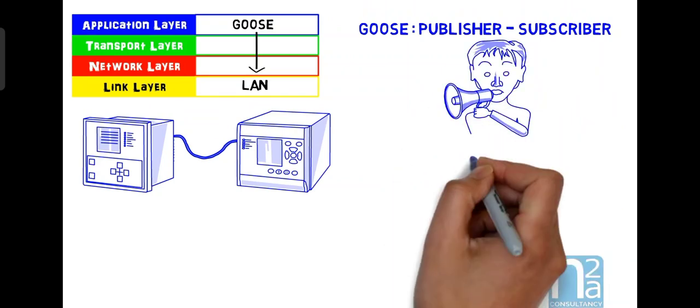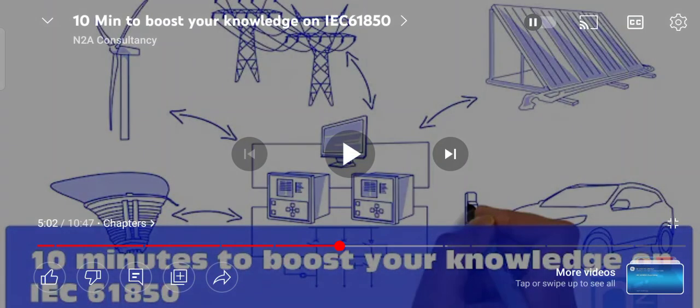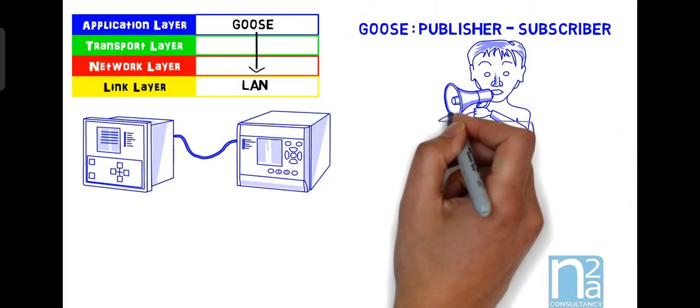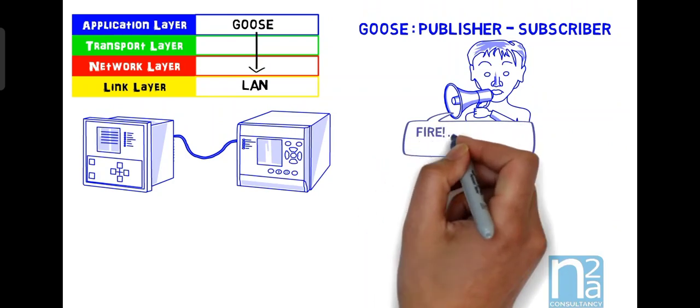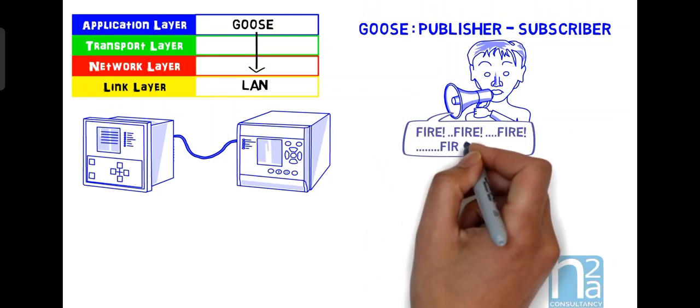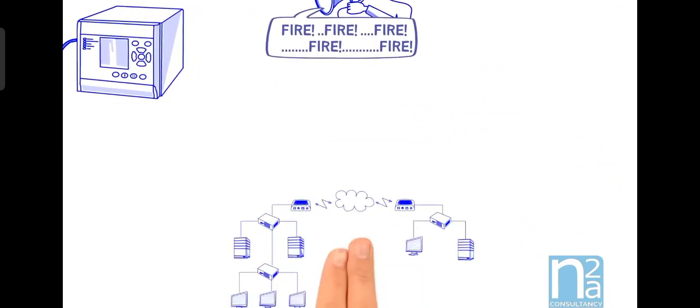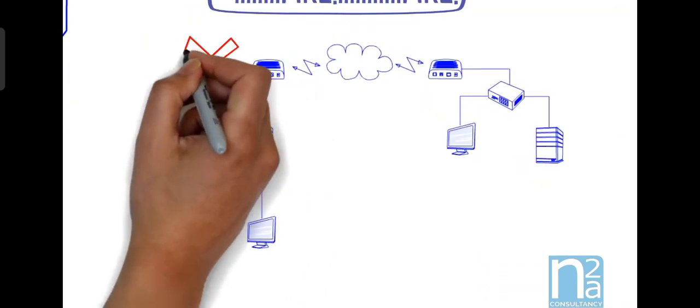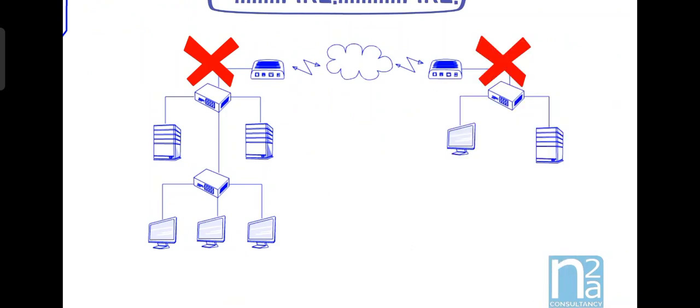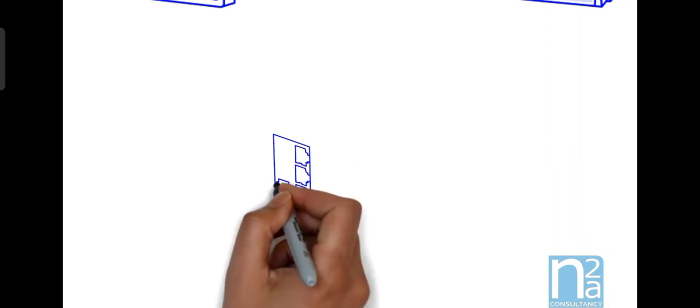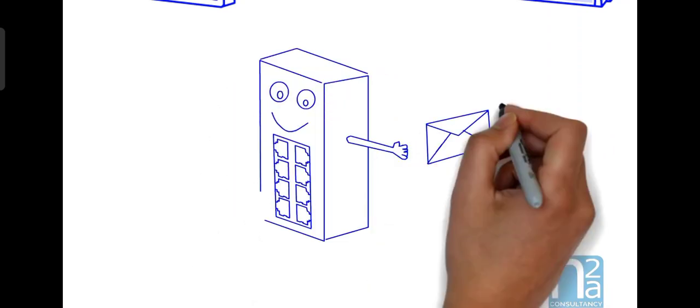Instead, the message is repeated during a certain time with an increased frequency. Lost messages are analyzed and reported later on thanks to their time tags. As the network layer is bypassed, GOOSE messages cannot hop across routers and stay in the local area network. But, as the link layer encompasses the priority tag, GOOSE messages are given priority by the switches.